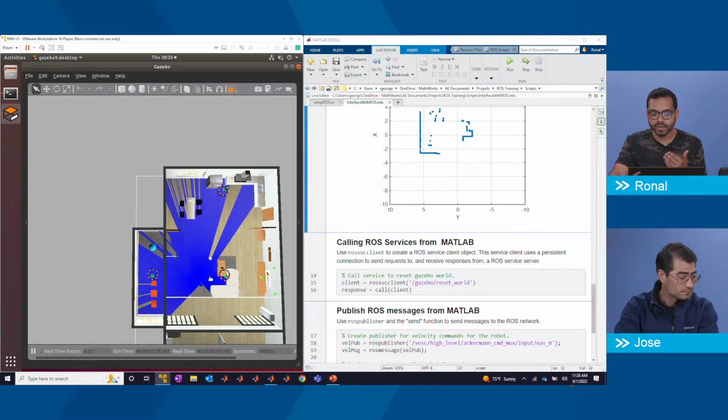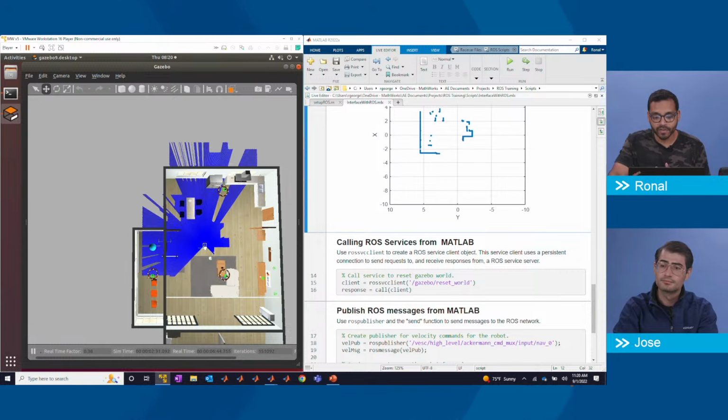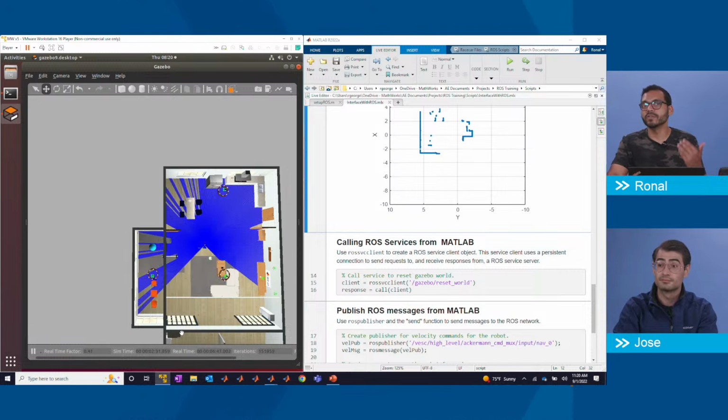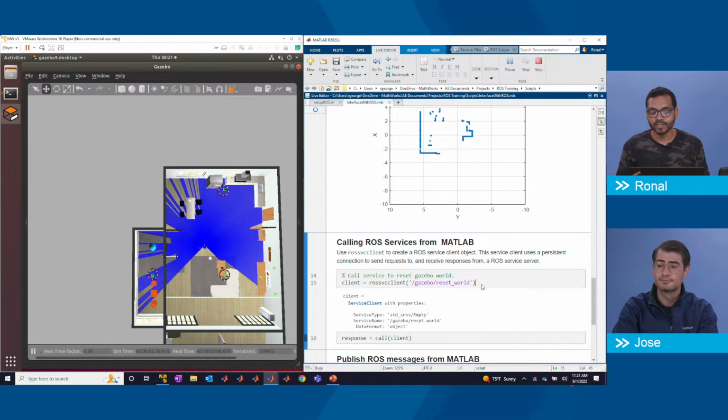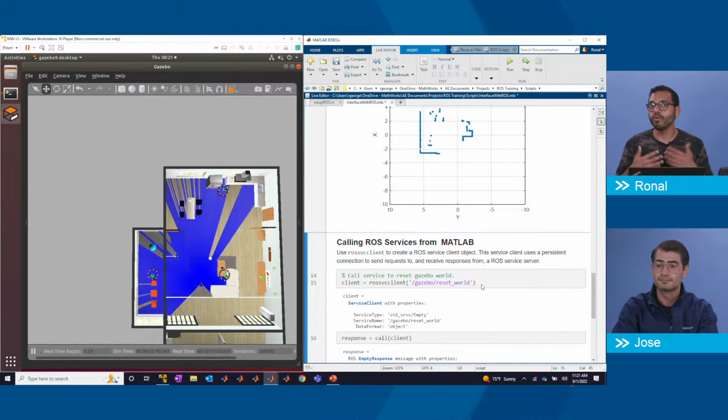All right, so you can do something else, too. Because we're working in Gazebo, let me move this little guy further up. So I've reset the position of this robot. What we can do in Gazebo with ROS is use something called services. These services are sometimes launched directly with Gazebo. Services are slightly different from subscriptions or publishers. A service is going to do an action that you've pre-decided. So here, this service is just going to reset my scene. Once I enter that, you can see that the whole world was reset.